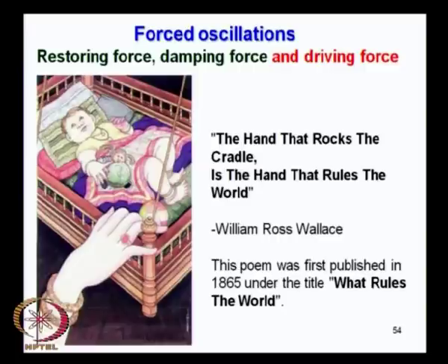here you have an oscillator which would oscillate under its own internal parameters, but then there is also some friction at the support, other than the fact that the air and the atmosphere in which it is rocking would also impede the free movement. But more than anything else it is the friction at the supports which will cause the damping.